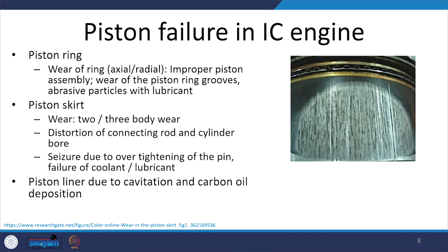So, if we see, this is the piston where the skirt of the piston has been subjected to the wear lines. So, the consistent and continuous loss of material in this manner will be leading to the loss of dimensions and shape, which in turn will be promoting the loss of the power being generated and eventually the failure or the fracture of the piston. So, what is important, what is causing the wear?